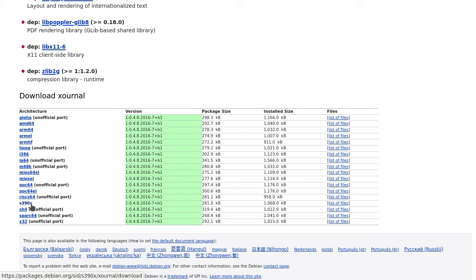I encourage all of you, if you have access to a circuit breaker at home or at your apartment, go open up the circuit breaker and look at the rating of a particular circuit breaker. What is the biggest circuit breaker that you can find in a normal household circuit breaker panel? 20 amps, okay? Most circuit breakers will pop at 20 amps. So in other words, you need 2 circuit breakers dedicated to only your room